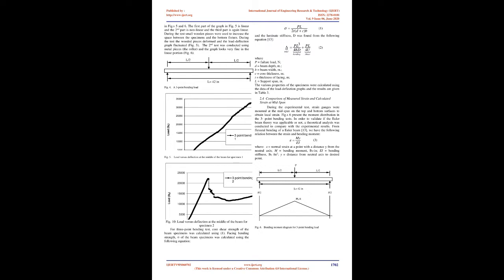In the absence of any delaminations in the sandwich structure, the buckling strain of the debonded region is shown to be the key parameter in assessing the structural integrity of a sandwich component in compression [7]. Effects of material properties and initial imperfections were examined in that study [7]. Analyses of the buckling of a delamination suggest that the effect of the core can be ignored. In contrast, the results showed that the core could not be ignored in the case of buckling of a debond, nor could it be simulated in terms of simple boundary conditions.